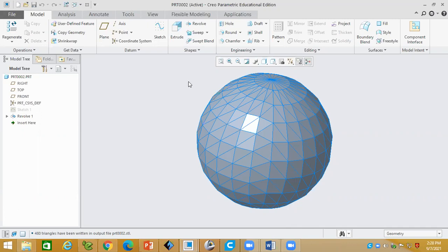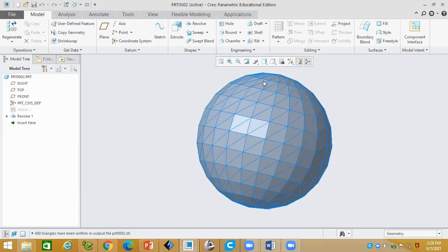If it is a normal plane surface, there is no issue. But if it is this type of curved shape, when we are converting from the CAD model to an STL file, we have to control the parameters in the CAD modeling software. Then we can get accurate data. Suppose I'm going to print this part, after completing the 3D modeling, you are not getting the proper shape. It is not looking like a smooth surface. For that reason, you have to control this in your CAD model.